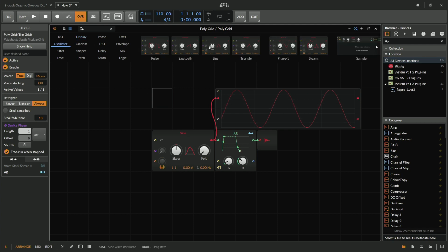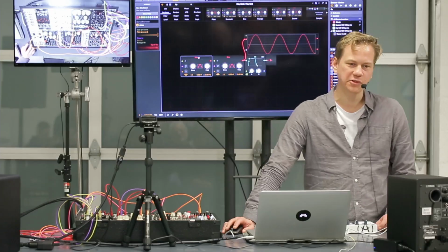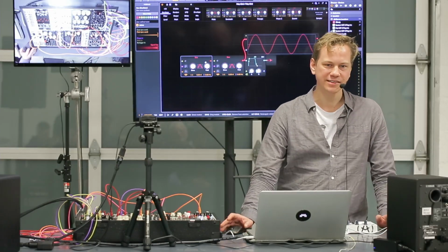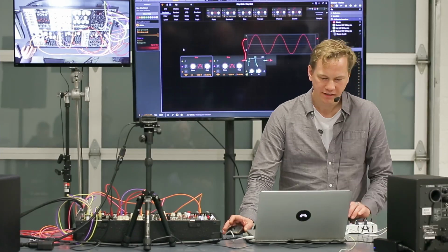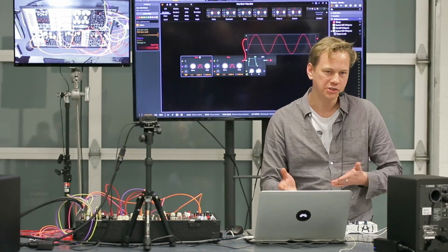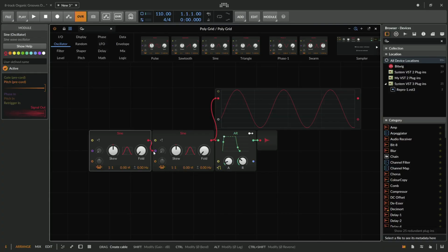Now, essentially, frequency modulation means one of two things. Either it's true frequency modulation, where we actually modulate the frequency, but most of the time it's actually phase modulation, like the DX7, which just modifies the phase, because it means that the pitch won't drift when you change anything. So if I connect this to the orange one, you get frequency modulation. If you do that, then it starts drifting off and does weird things. But if I connect it to the phase input, it just stays here and modifies the waveform.